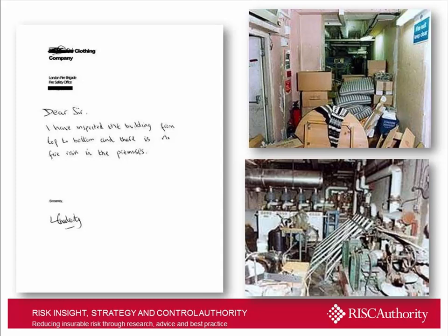So clearly, certain individuals have a very different view of what fire risk might be than what we might perceive it to be, and hence the need for guidance and codes and steerage so that people understand exactly where the issues lie. But that particular fire risk assessment is really a requirement of the Regulatory Reform Fire Safety Order, where there's a requirement for you to do your fire risk assessment, and that is very much focused on the life safety elements of fire safety and ensuring that people can get out of the building effectively in the event that there's a fire.